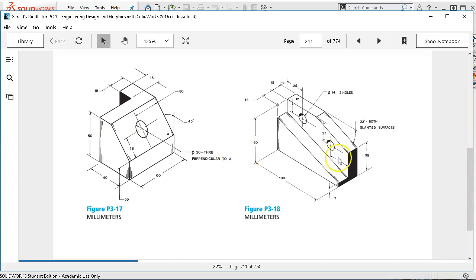Alright, going into 318, look at this one and we can split it right across the face, and then our geometry becomes dealing with the front wedge and the back and placing two holes. So this one's really good for the contour and regions, in that we can generate all of this geometry. A nice rectangle with the corners and the lines, and build out from the front plane, and then build back from the front plane.